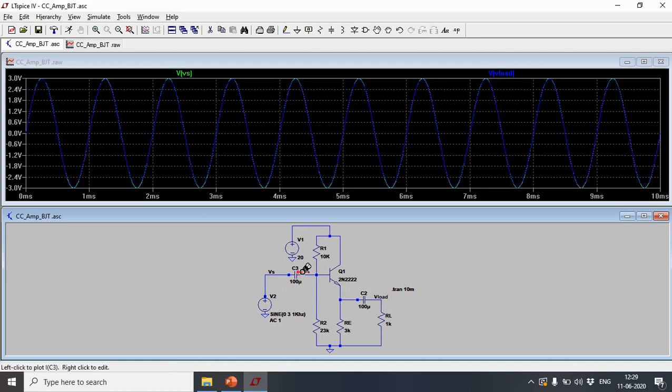Obviously power cannot be created or destroyed, so where does that additional power come from? That additional power is taken from the source, from the VDD, right? If you see, the power which is drawn from this source is very minimal, whereas the power available at RL is large. It is large because of the higher currents, and that extra power is not created through magic or something. That power comes from the VDD which is connected out here.